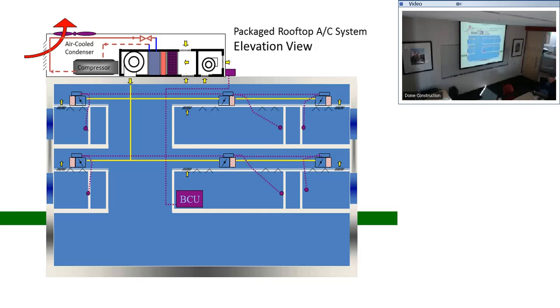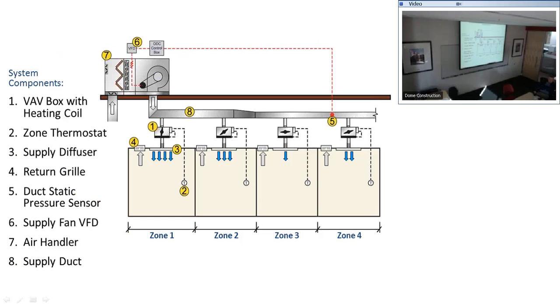Exactly. From a GC perspective, one of the major things I see issues with on a unit mounted on a roof, especially large ones, is maybe the vibration or noise. So you should ask the question: if you're doing a down discharge, has the contractor figured for potential breakout radiated noise that's all hit the space, or are they going to need a sound consultant, or do you need to have vibration isolation on it? Those are the big considerations. You're asking a contractor what he's providing for that, what he has done to take measures for it.